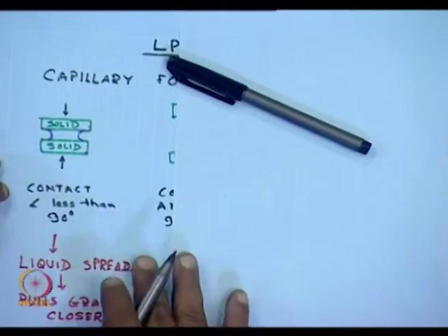So, as sintering proceeds, the surface gets more and more wet. What is the consequence of that? The consequence is simply this: if the liquid is wetting the grains, they are pulling the grains closer. Say you have dry sand, it occupies a certain volume, you pour water on it, and the sand packs.